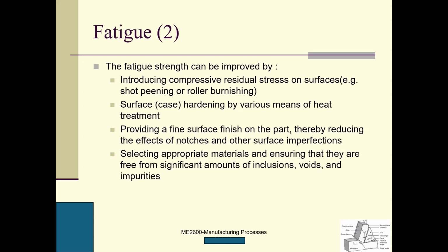First, the chamber, and then you put your workpiece here. At the same time, you put either liquid, solid or gas that are rich in carbon atoms, and let these interact with your workpiece. Then you seal the chamber and elevate the temperature.